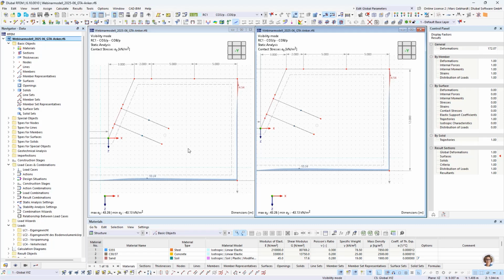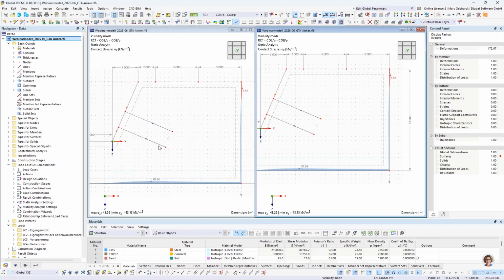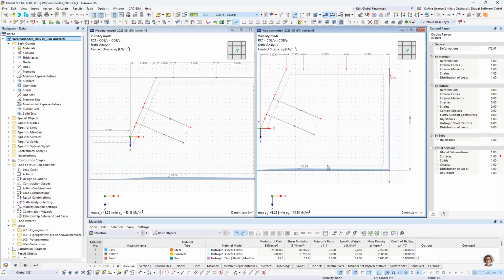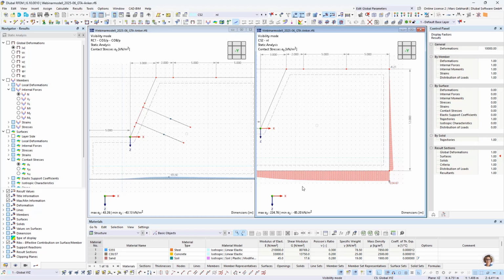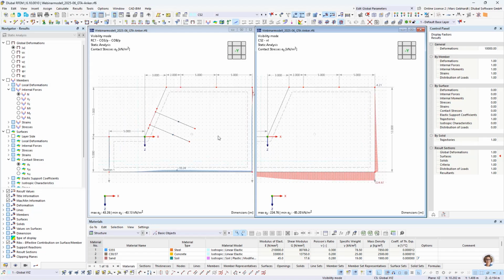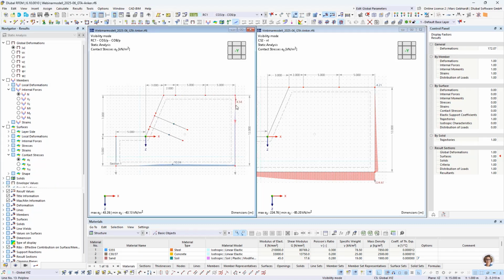And here we see the stresses, the additional stresses from vehicle load, and here we want to check the self-weight of the soil. And see, here we can show each results, but we can, as you see, it's much less than 10% on the bottom. We only have a higher point on the upper right.